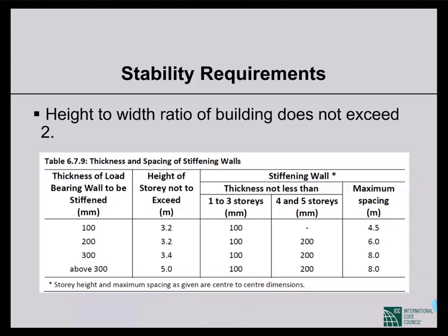And since in the design of walls we don't want to consider the second order effects, but if we want to combine them, then we have to consider second order effects in wall design, and that is not easy. In that case you have to design walls quite thick, and that is not feasible or economical either.